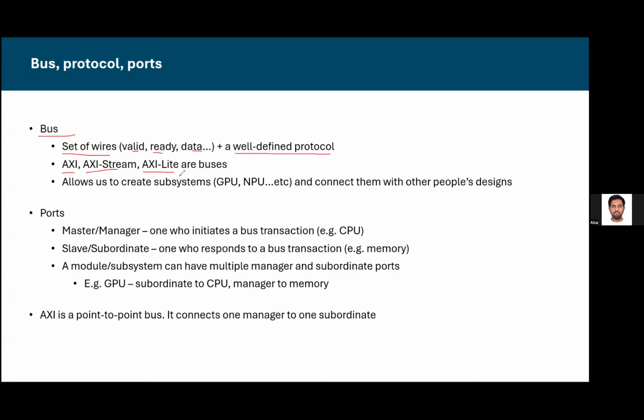Okay. All right. And having this set of standard wires and standard protocol helps us create these subsystems. So you can create GPUs, NPUs, systolic arrays, registers, whatever you want, right? And if you're designing your own stuff, you can create it and connect it with other people's designs, right? This is why ARM created these buses.